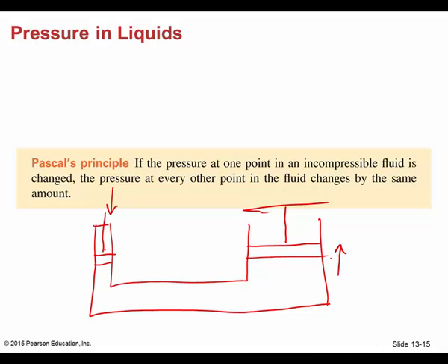So if you recall from our equation that pressure is equal to the force per unit area, then guess what? The pressure at one point is the same. It goes unchanged. However, since the area of this piston is much greater, we actually multiply our force. Okay, even though the pressure is the same, you can take a very low force and raise something that is very massive. Okay, does that ring a bell with anybody?